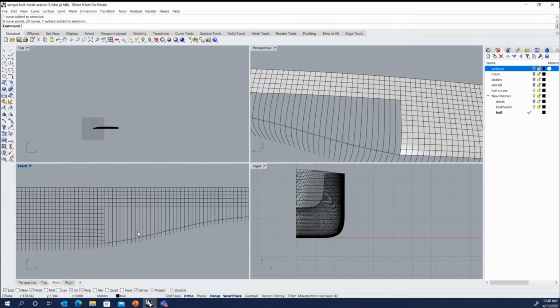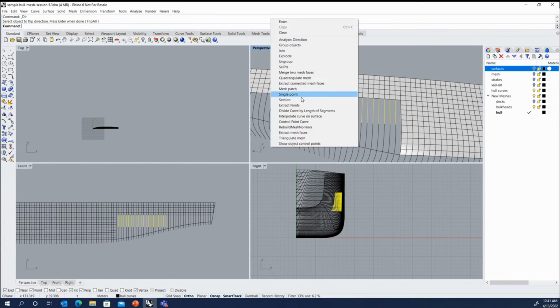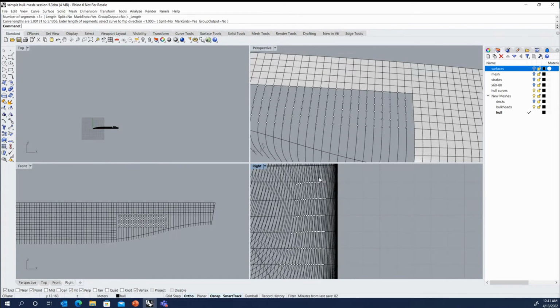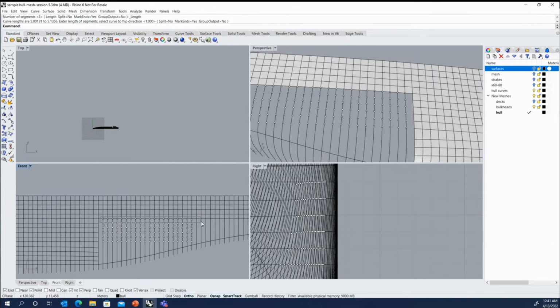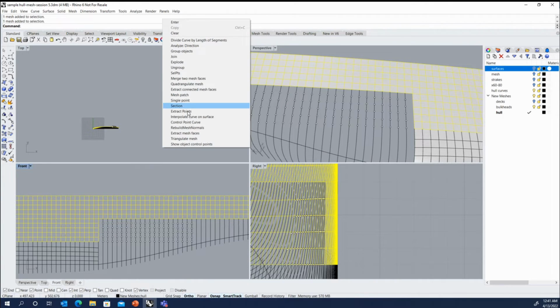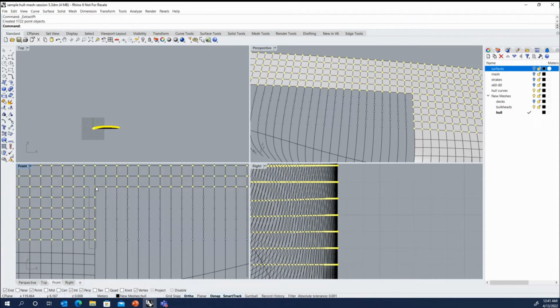Let me check the direction. I'll point up so we can use the 1 meter length of curves. Again, they're not quite touching the mesh there, so we'll do that same trick to delete the top row. And here we're going to extract both this and forward, so we get these points and those points. And we'll just do, we still have extract points available. Select these.